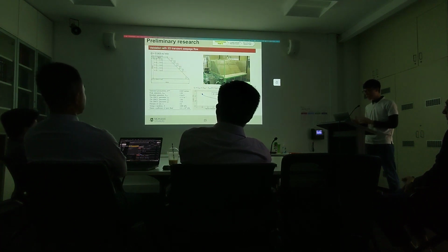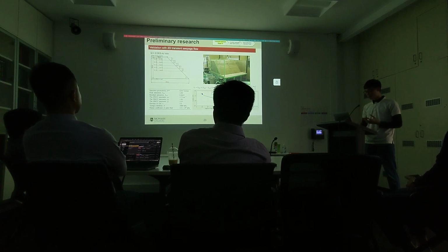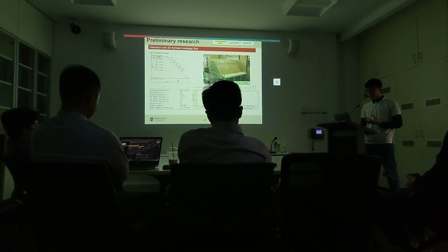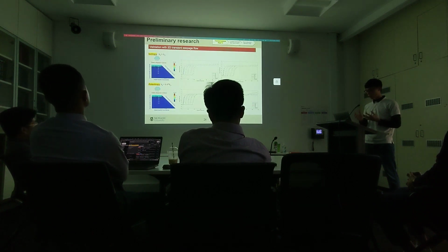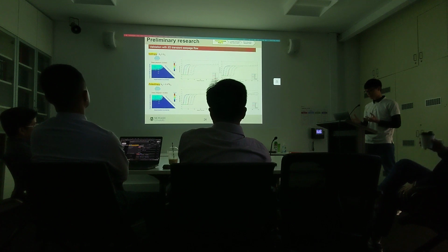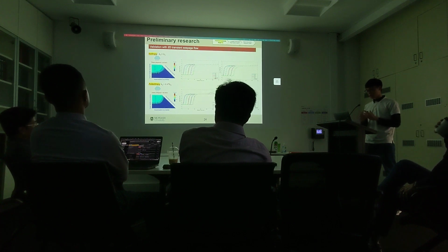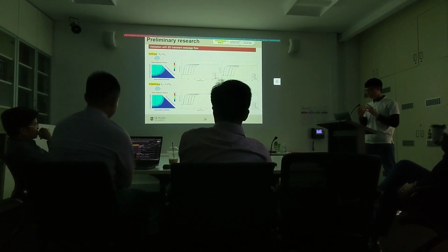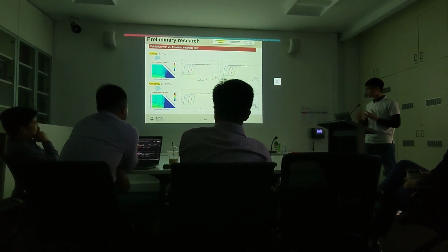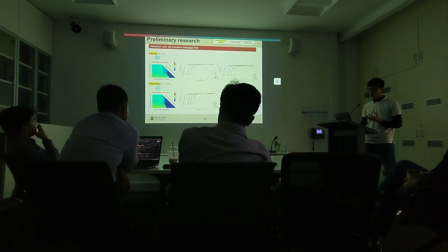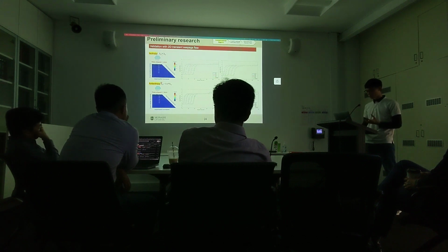Next, we validate with two-dimensional transient seepage flow against experiments. This is the experiment setup from Keaton Ray 2007, and the listed parameters here allow us to calibrate our soil water retention curve. First, we compare results with the finite element method. You can see from here the excellent agreement between the two numerical methods, suggesting that our developed HPX model can capture well the change in seepage flow, not only isotropic but also anisotropic.